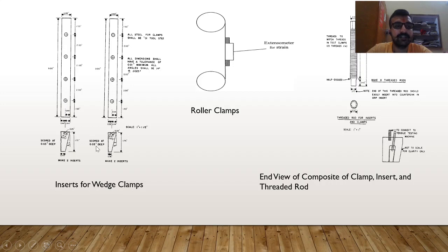As I've discussed the clamp, these clamps may be modified to provide greater ease and speed of clamping. In any event, caution must be taken to ensure that the type of material and the dimension of the clamp are adequate for the user's expected fabric strength and size. Each clamp has jaw faces measuring wider than the width of the specimen, that is 8 inch, and a minimum of 50 mm (2 inch) length in the direction of the applied force. Here is the roller clamp on which your textiles will be installed.